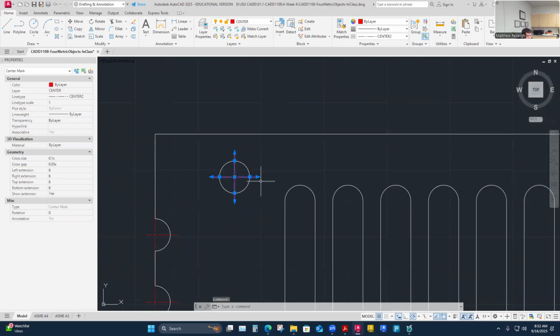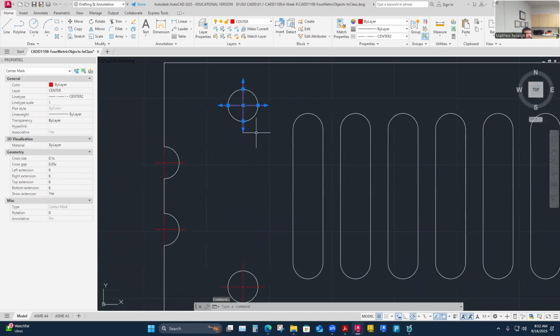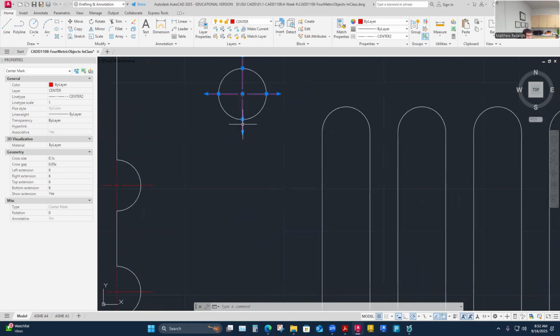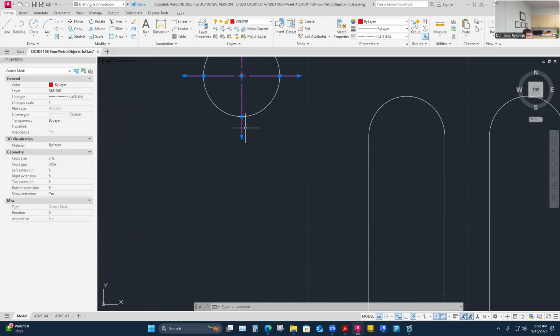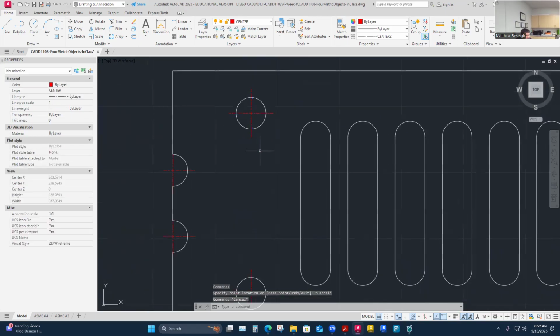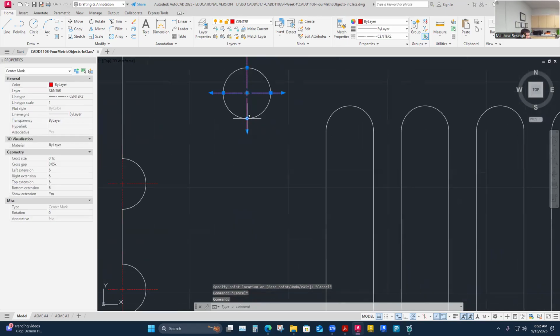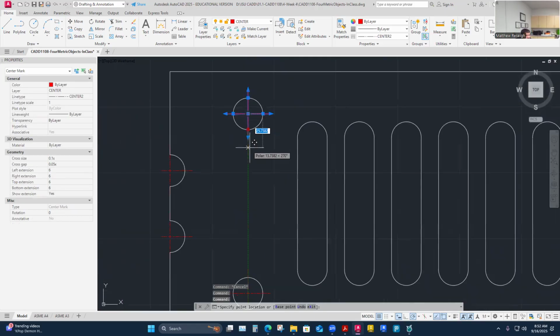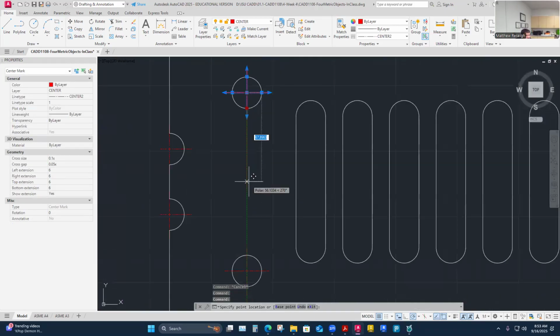So I'll do that. And I'll probably share the difference here: I think I'll pull it from this grip. You could pull it from this grip too. I like to pull from this grip because I like to keep that 6 millimeter relationship here in case I need it. And if I pull from here, I'm actually affecting that 6 millimeter relationship. So what I do when I pull these together is I tend to pull it from the actual end, not from the extension.